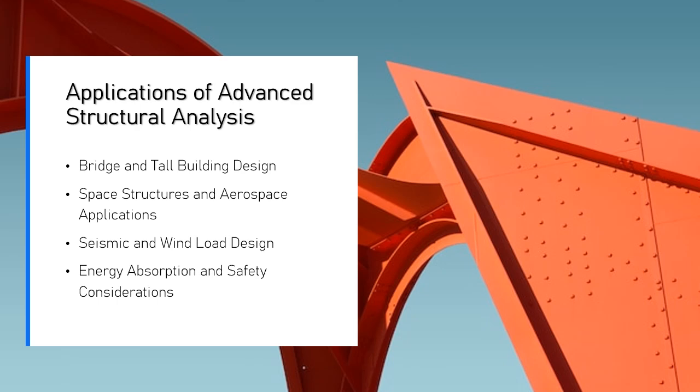2. Base isolation systems. Base isolation is another technique used to decouple a structure from the ground motion during an earthquake. By introducing flexible bearings or isolators between the building foundation and superstructure, base isolators allow for relative motion between the structure and the ground. Challenges.